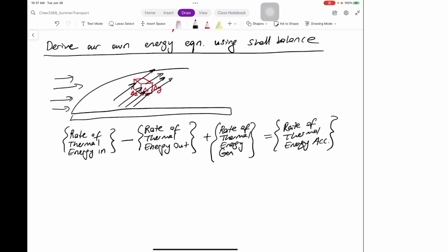There's going to be heat transfer just because of the motion of the stream, the stream itself getting into the shell and coming out of the shell. It's unlike the conduction we have done for the solid objects. Yeah, that's advective flow. So that's advective heat transfer that we are taking care of right now.